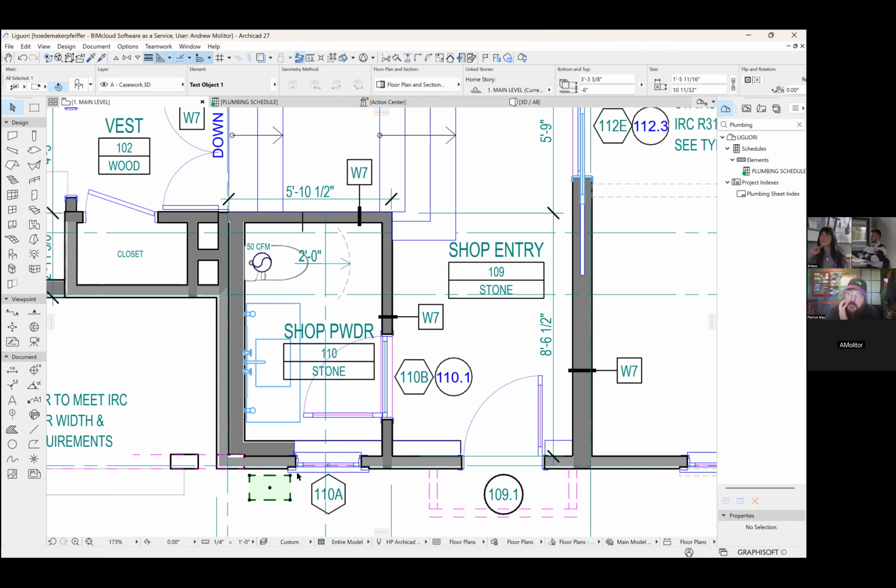If you draw it in CAD, it is possible to bring those CAD blocks in as new objects. And if they come in as objects, then yes, they could schedule. But if they come in as lines and fills, it's not going to populate the schedule. Okay, I see.